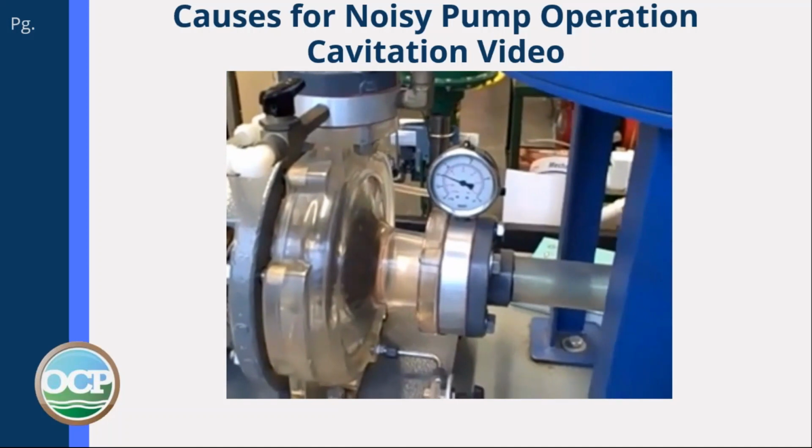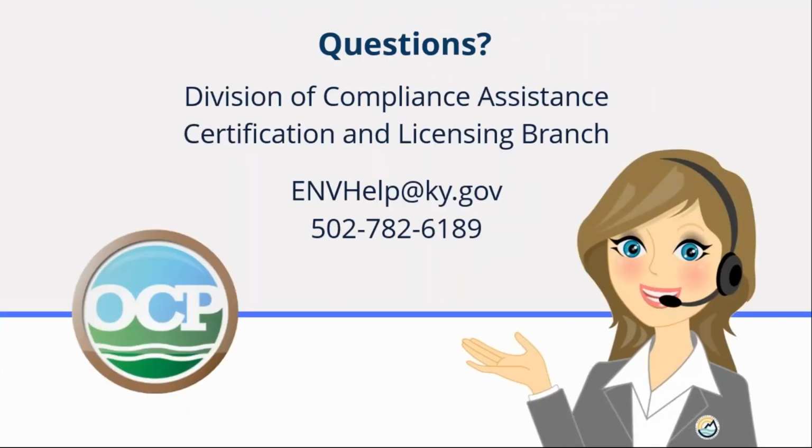Cavitation, like he said, is very destructive to pumps and impellers. I've actually seen the volute of a centrifugal pump be blown apart from cavitation, from the collapsing of those air bubbles that are formed. It's amazing what air bubbles will do. And that's the end of Pumps and Motors in Chapter 9.